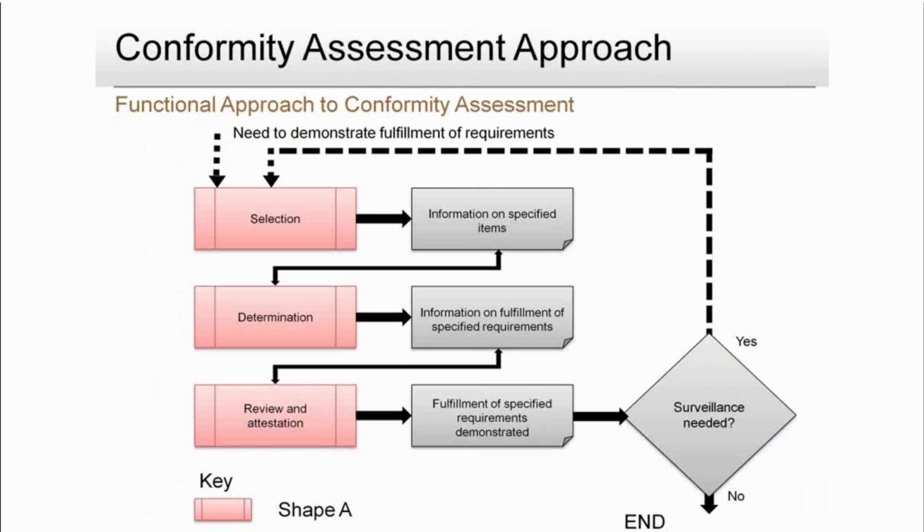As much as possible, it's advised to use appropriate test methods, mostly standard methods. And in cases where non-standard methods are used, those methods must be validated. There has to be validation before you use these methods in the laboratory. There is also estimation of uncertainty, also related to test and calibration methods. Basically, there are two ways of estimating uncertainty.